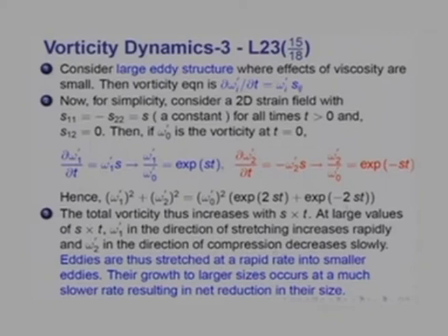What does this tell us? This tells us that the eddies are thus stretched at a rapid rate into smaller eddies. Their growth to larger eddies, however, occurs at a much smaller rate, resulting in the net reduction in their size. Now, this is a very important observation to make from vorticity dynamics.